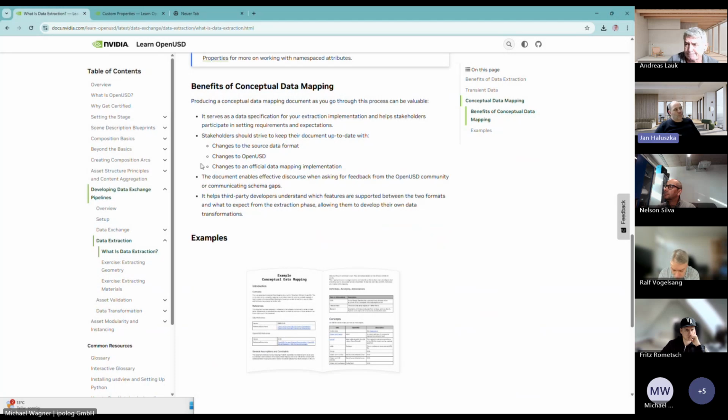For instance, what I'm doing right now: I've got a customer that has data from Cinema 4D, and he wants it to be transferred into USD. The problem is not the mesh. The problem is the material. I create a dump JSON file from all the material properties, and then I transfer it with my own translator into an OpenPBR surface. So you can do those kinds of things.